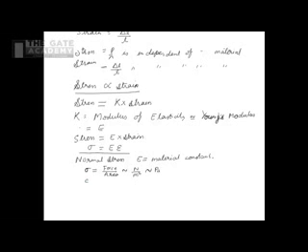Now let us see the unit of strain. Strain is change of length over original length. The unit of this will be meter over meter, which means dimensionless. So strain is dimensionless and stress has a unit of pressure, or let's say Pascal. So E, which is nothing but sigma over epsilon, will have the unit of stress then, which means that it will be having the unit of Pascal or pressure. This is about the unit of E.